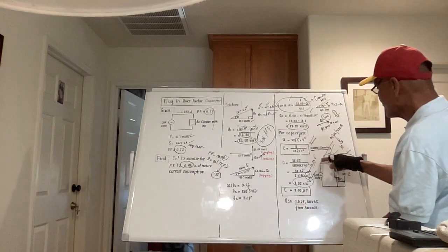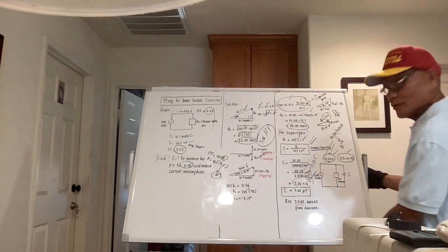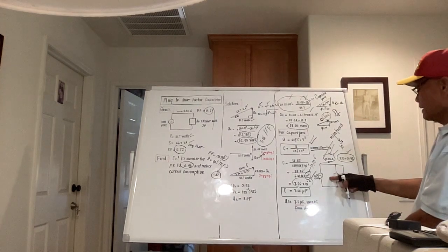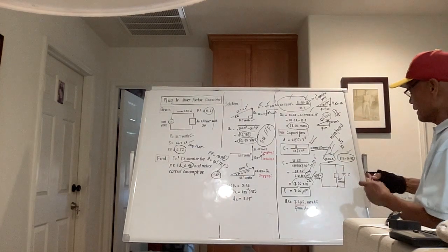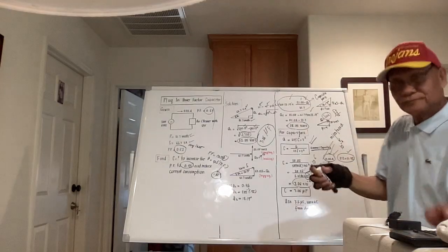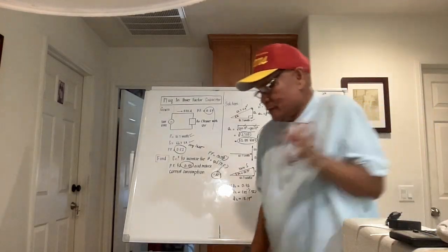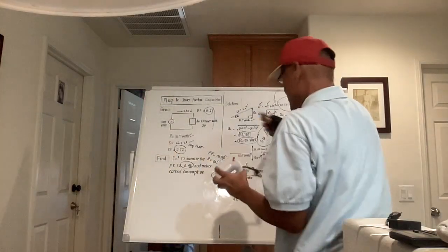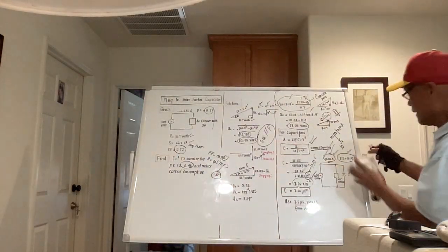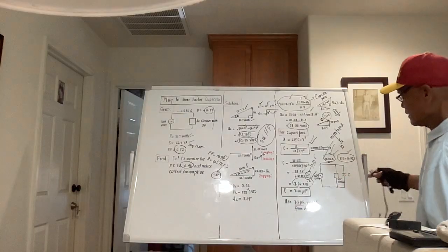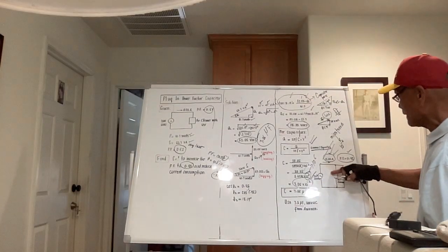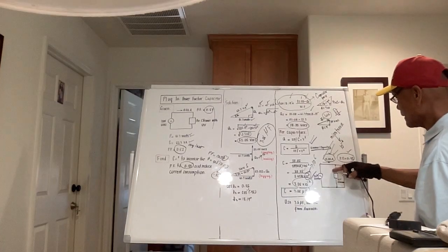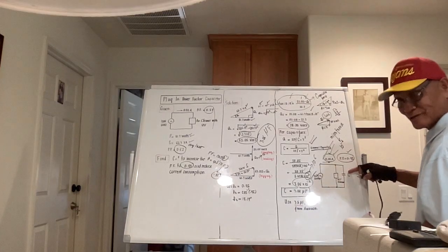So this is the circuit with the power factor capacitor placed. This is the air cleaner. I put in parallel a capacitor, the one I'm showing you. Since we got two loads, air cleaner and capacitor, the reactive power of the air cleaner is counteracted by the capacitor.